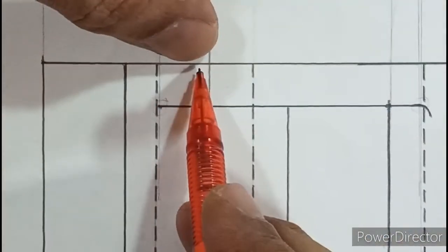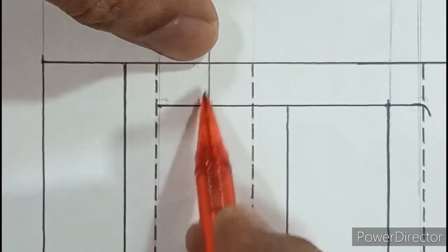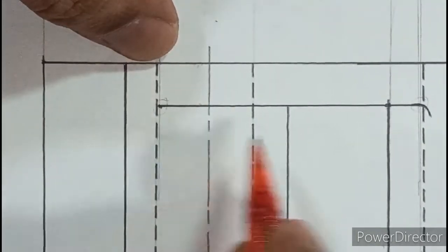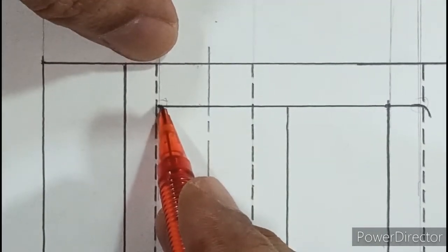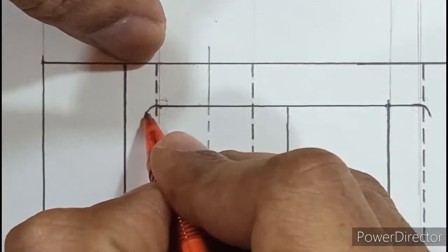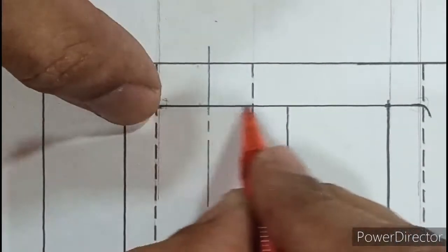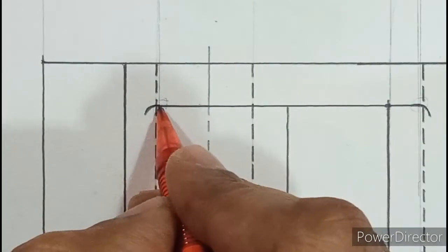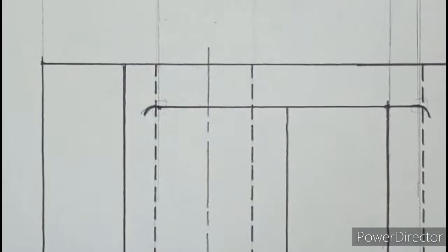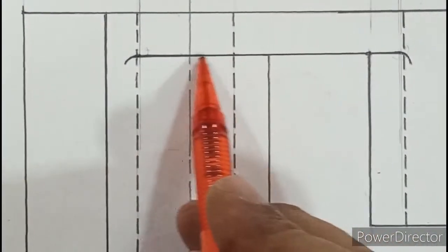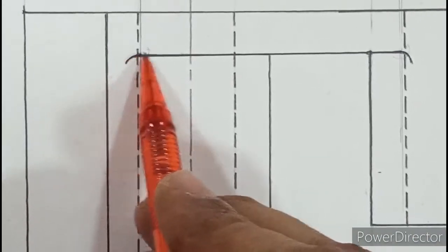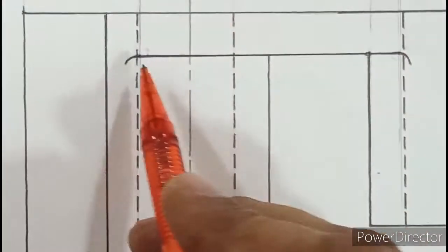Now look here again, a small surface of 10, so this thickness is 10, is merging with a large surface of 70. So the merging arc should be pointed towards the larger surface. The larger surface is 70. So beyond this you need to draw a freehand arc, beyond the straight line. You have drawn a straight line up to the merging point, beyond that you should draw an arc. So this arc should be drawn beyond the merging point. It is just a curve. Again it is a straight edge up to here, and beyond the straight edge you need to draw a small freehand arc on either side. So this is the symbol of merging.